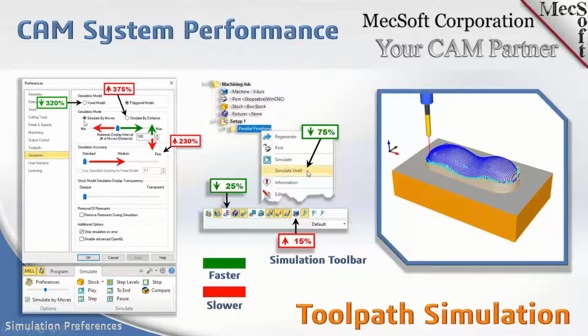Okay, let's take a look at the simulation mode, which a lot of users get confused about. You have 2 choices here, simulate by moves and simulate by distance. What this means is how many times the model gets refreshed on your screen. In the background, the algorithm is calculating all the toolpaths, going through the whole model, but you can control how many times it shows you the model while it generates the simulation. If you don't care to see the toolpath 35 times versus 5 times, you can really decrease the time it takes to get through that simulation.